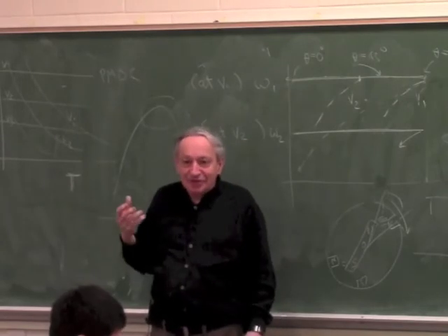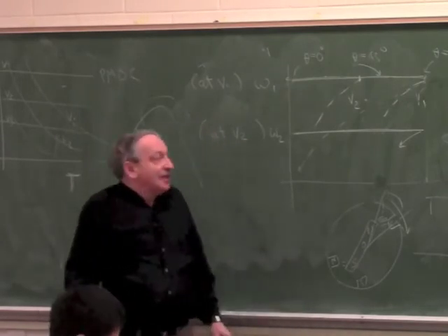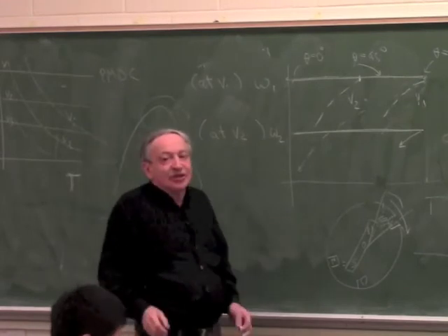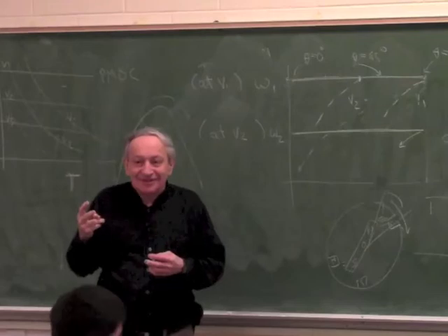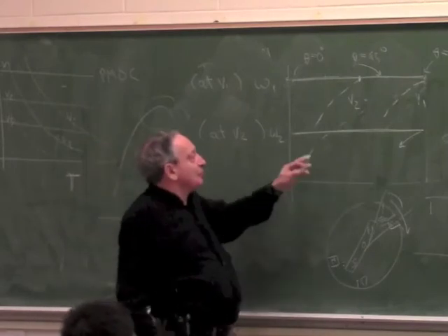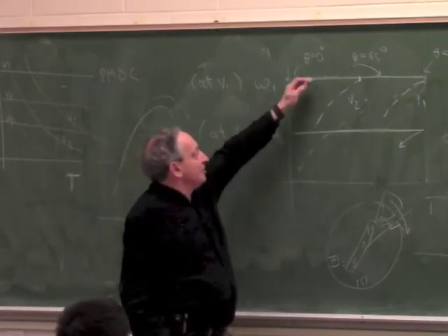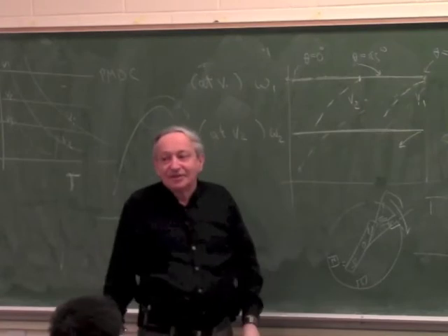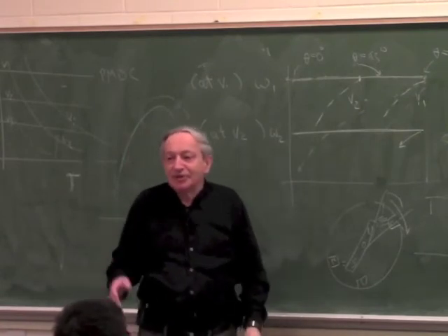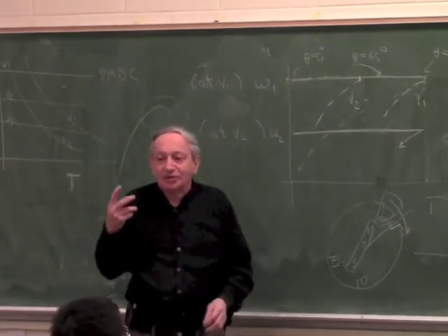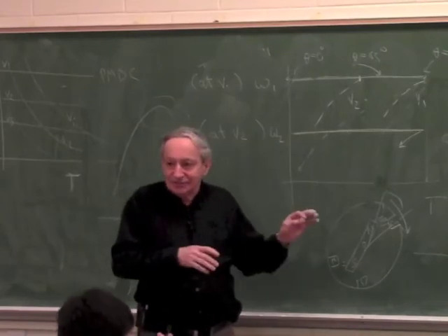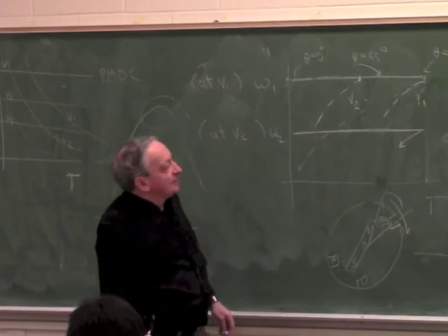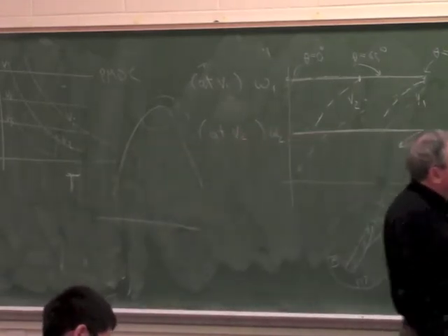So it's really 1 degree of freedom, okay? Now, in this motor, no matter what you want to do, you have to adjust 2 parameters. Okay, so if you want a new operating point, unless the operating point is the same speed, okay, if you want a different operating point, meaning different speed, different torque, you have to always adjust 2 parameters, the frequency and the voltage. Clear? Good. Okay.